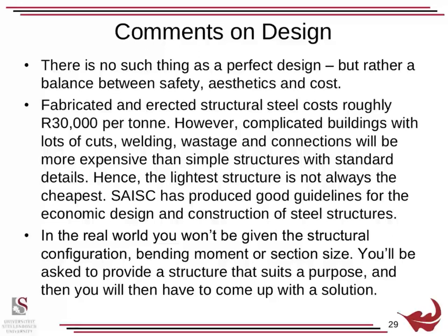And so fabricated and erected structural steel costs roughly 30,000 Rand per ton. This number's a couple of years old. It's probably a bit higher by now. But complicated buildings with lots of cuts, welding, wastage, and connections will be more expensive than simple structures with standard details. Hence, the lighter structure is not always the cheapest. The South African Institute of Steel Construction has produced good guidelines for economic design and construction.